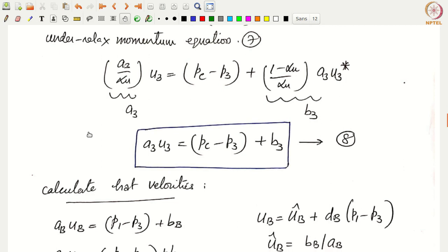Okay, so that is the significance of writing this kind of a half cell thing, which was of course not there in the staggered mesh case, right? Because the pressures and the velocities are anyway staggered, so you never had to do such a thing before. Okay, all right.